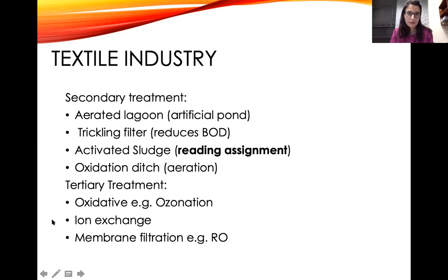Like it clogs in a year, so you do maintenance and change your filter after like every 9 months or so? You can't change the filter, but you can clean it. For example, with my PhD study, I was continuously cleaning the membrane with acid-based solutions, basic solutions, to make sure that every time I run a filtration setup, I have the membranes completely clean. So the cake doesn't build on it.